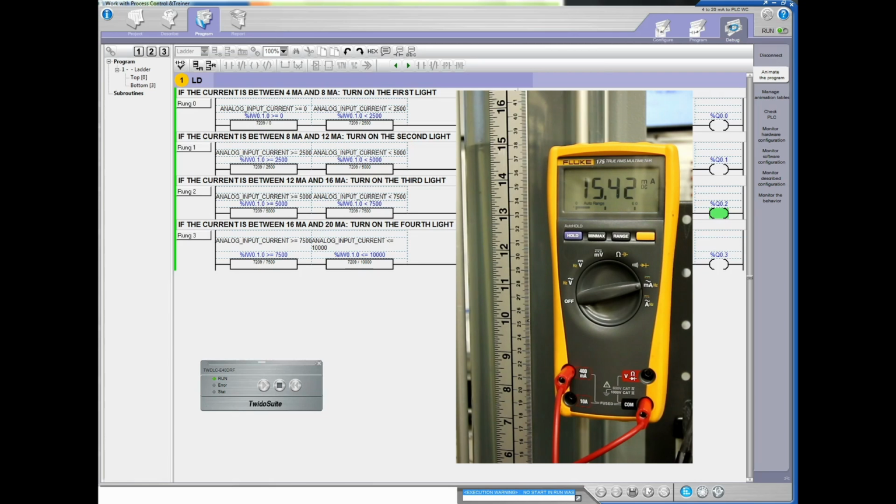and we'll drop the level down again, and we should see at 30 centimeters that we get 12 milliamps. Beautiful. So there's 30 centimeters corresponding to our 12 milliamps, and what have we got on our PLC here? That looks good. 5,014 for the value coming in. So we're half of our 4 to 20 milliamp range. So we're half of the 0 to 10,000. Everything's mint.